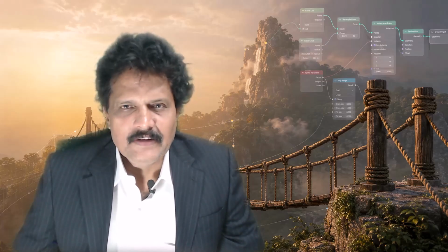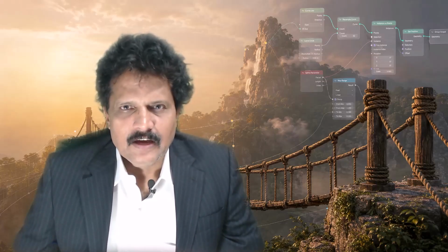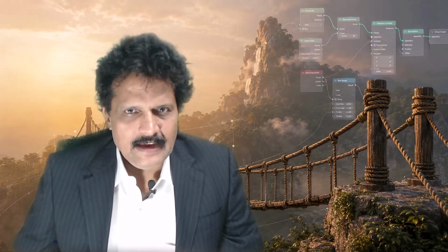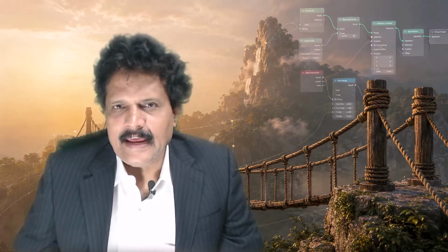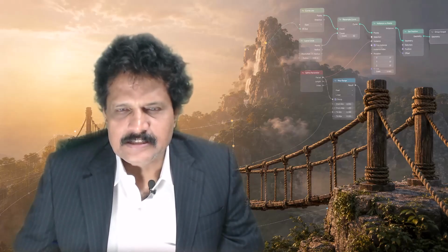After that, we will create 4 corner pillars that hold the ropes for the bridge. These pillars will not be placed manually. Instead, we will generate them procedurally using curve line, curve to mesh, curve star, instance on point, and endpoint selection. The most powerful part of this session is that pillars will automatically follow the bridge.